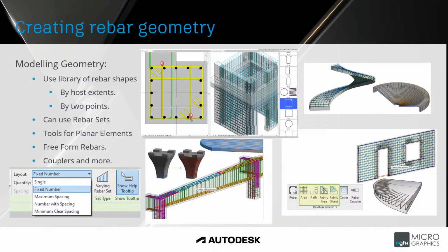If you space these rebar sets along the beam, it'll have the same size, but as soon as you click the varying rebar set on the little image there on the left, it will then expand and adhere to the size of the shape of the beam as it goes along the beam, covering the extents of the size of the beam.